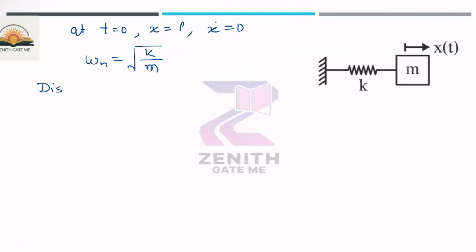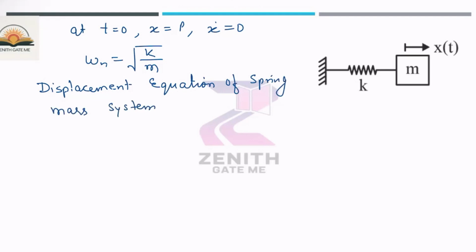Now the displacement equation of a spring mass system is given as x equal to A sin ωn t plus B cos ωn t, where A and B are constants that you will find out by using the given conditions.